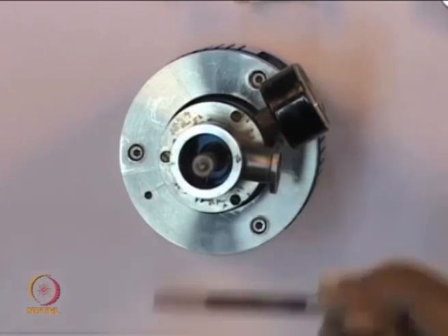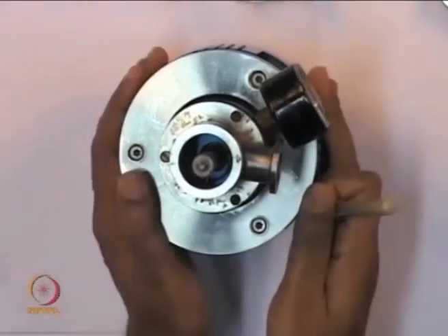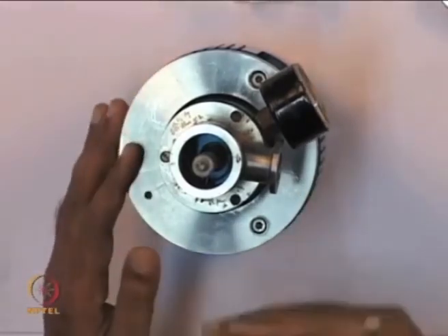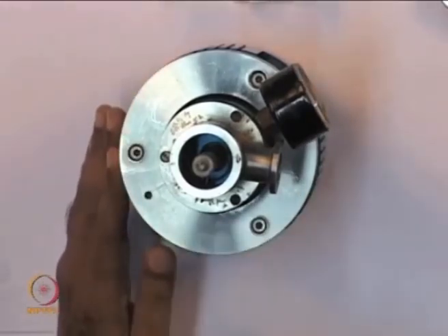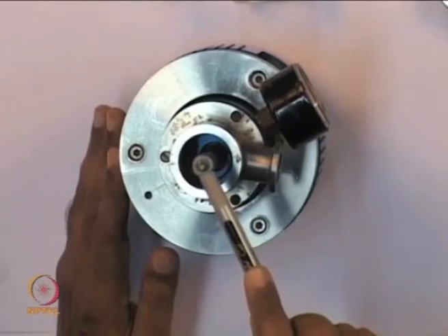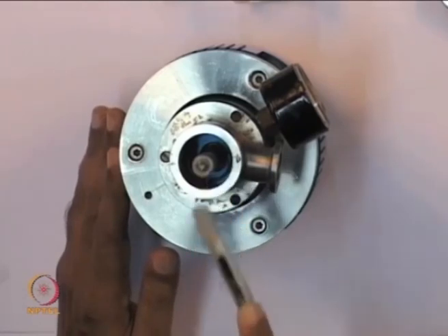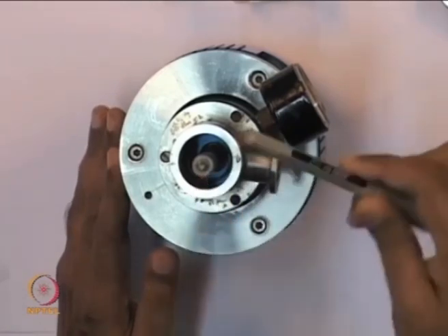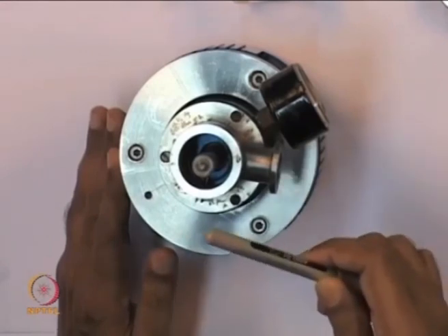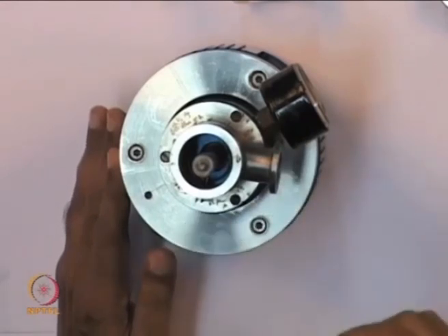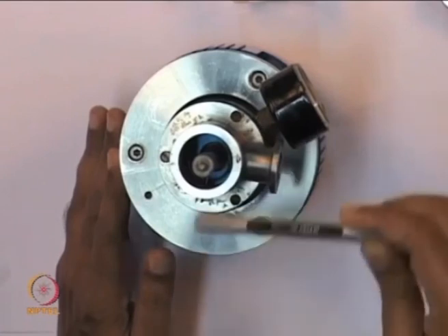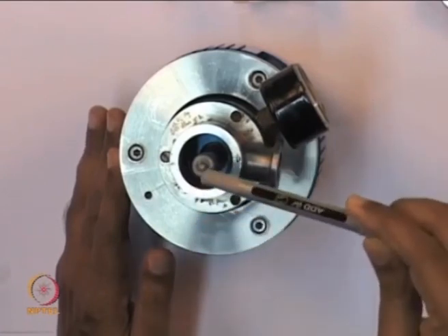In a closed cycle manner, a gas, which is helium in this case, is continuously compressed and expanded in order to produce 80 Kelvin temperature at this point. So, this is nothing but a closed cycle cooler which works on the Stirling cycle. That is why I call it a Stirling cooler, producing around 0.5 watts at 80 Kelvin.